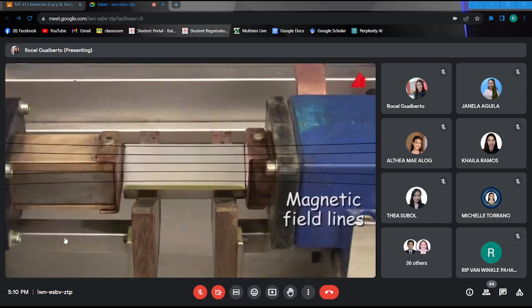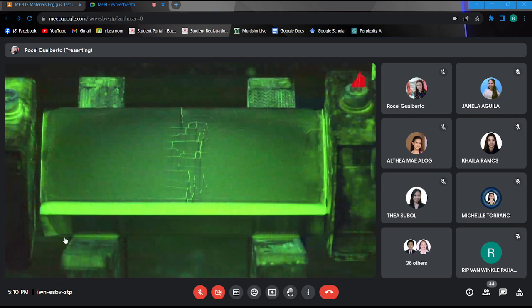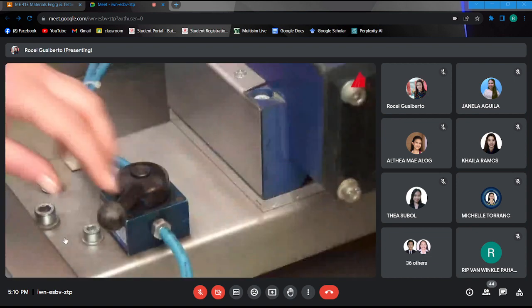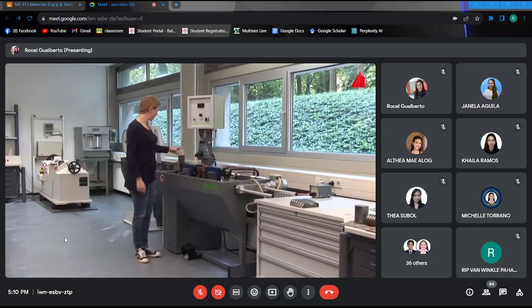Our test sample has been magnetized in horizontal direction. The magnetic field lines run horizontally. This is the reason why cracks in vertical direction are visible particularly well. To make sure to detect all near-surface cracks, one has to magnetize the sample once more and best perpendicularly to the first time. To do this, the material tester switches the machine over to the current flow method.